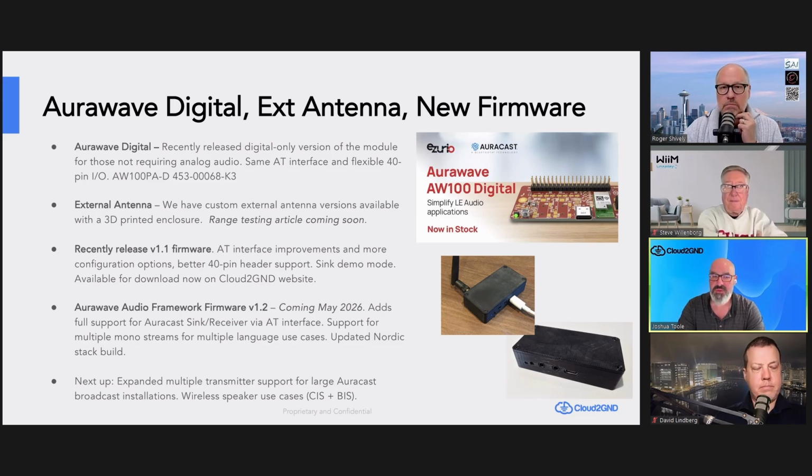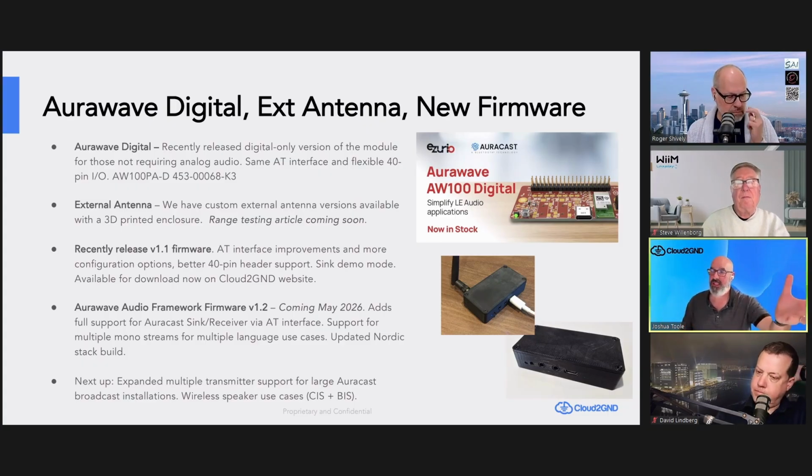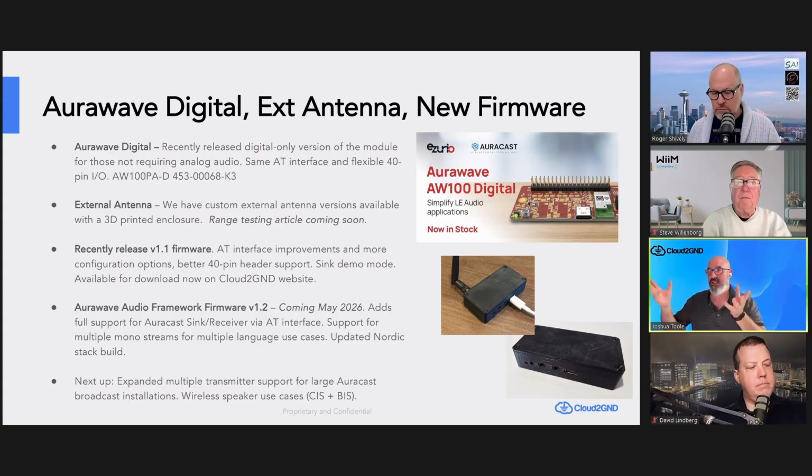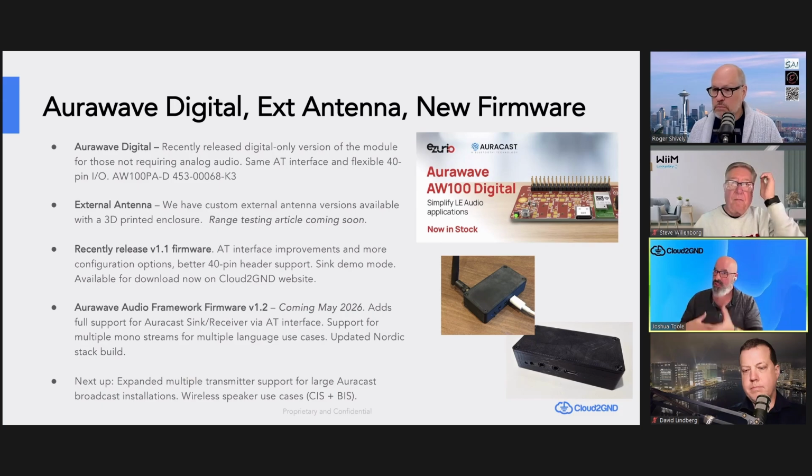Yeah, that's right. So essentially, the receiver device will know that it's listening to a certain broadcast. That broadcast has an ID, and it's able to look at the fact that, oh, I see two instances of that same broadcast ID in my radio space, and maybe this one has a higher signal strength than this one, and so I connect to the one with the higher signal strength. Then as those signal strengths change, I do a transition, right? The additional work is about making those transitions seamless, just like when you're roaming on a cell network or moving through a larger Wi-Fi installation, that's transparent to the user, right?